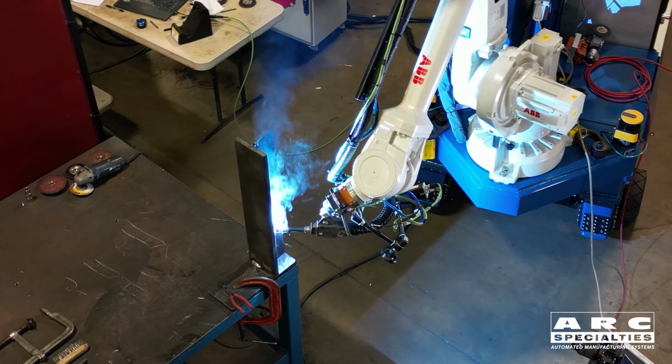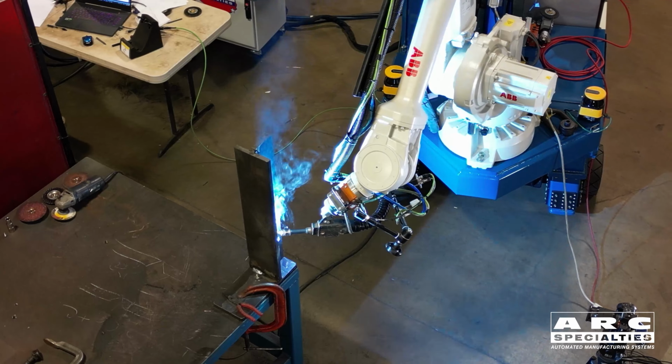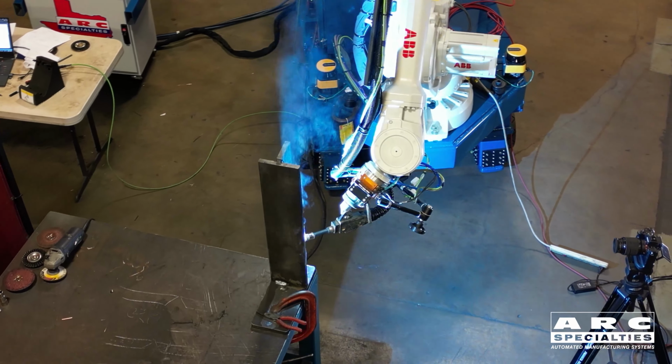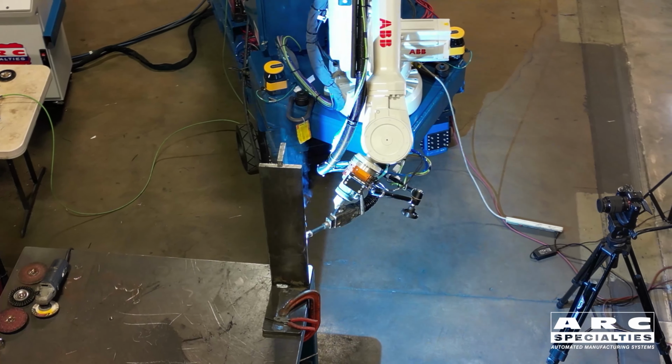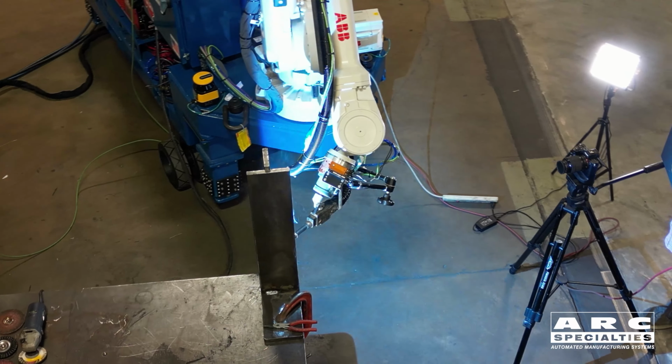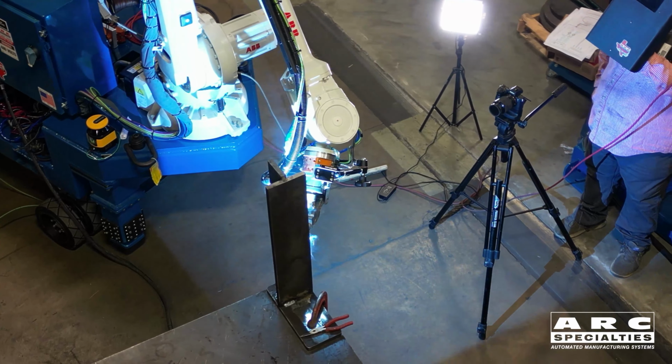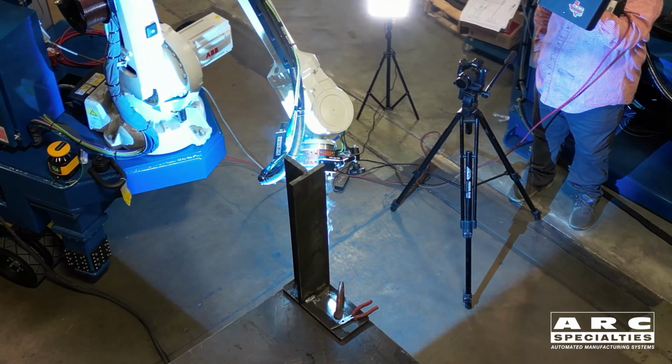The solution to the arc light problem is to let the robot do the welding. The solution to the fluidity issue is to use pulse current and reduce your overall heat input. With pulsed welding, you actually only transfer a droplet of metal across the arc with each pulse. This allows you to weld vertical, overhead, and in any position you'd like.